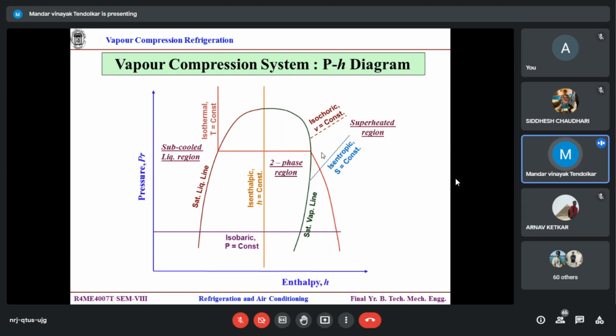Fine. So our cycle analysis, the per compression cycle analysis, deals with isentropic compression, then isobaric heat rejection, because condenser pressure remains the same, even though the state may be somewhere here, let's say, superheated. Pressure would not change. It's a heat exchanger, it is rejecting the heat. Why would pressure change? Correct. So I will say isobaric heat rejection, then isenthalpic expansion, and then again isobaric heat addition.